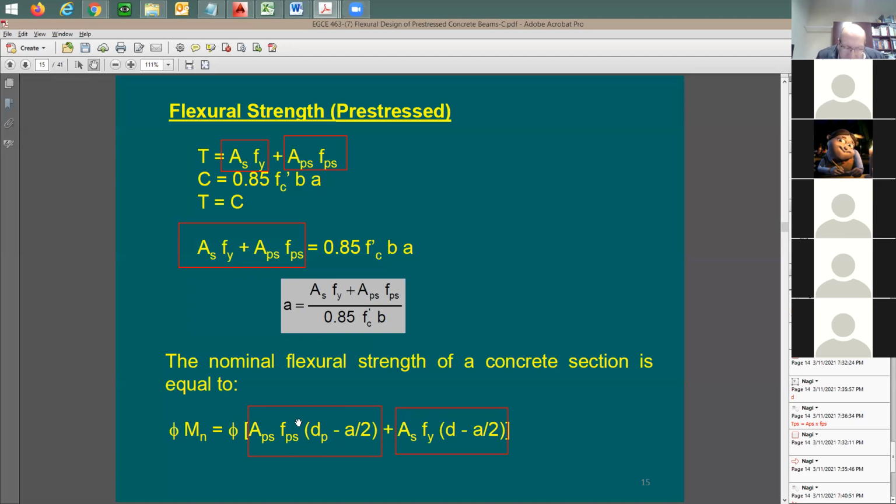Which one is for the APS? The conventional? Yes. Now, this pre-stress strand is going to be much stronger than this, right? Absolutely. All the grade is going to be 270. For the conventional rebars, the grade is going to be 60. I'm going to say, why would you add this if this is going to be enough? I mean, you have lots of these. For each one of this one, it is equivalent maybe to 3 or more than 3 of this rebar.